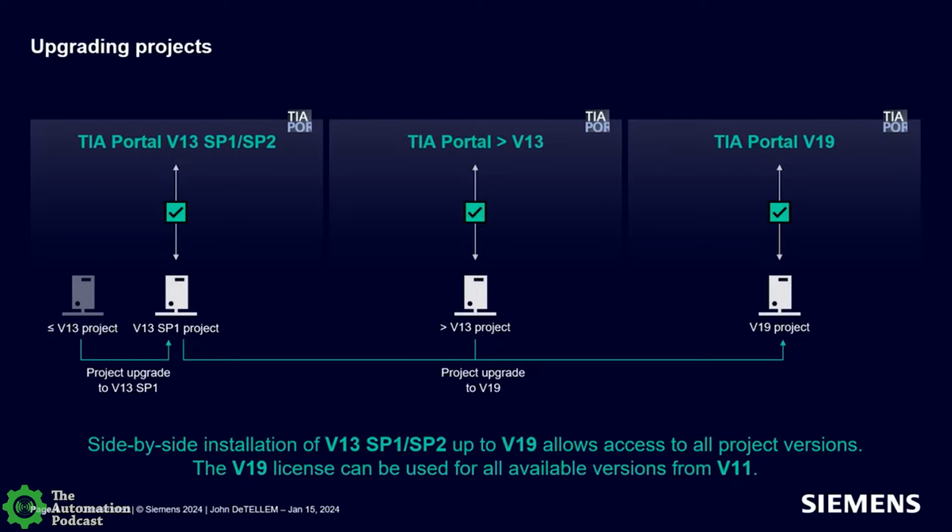So even though I order a brand new PLC, a 1512 compact CPU, and I get the 3.1 firmware that works with the v19, you don't have to do any flash backwards or firmware adjustments. You just apply that hardware to your v17 environment with the latest and greatest firmware that's supported in v17, and the hardware runs in compatibility mode.